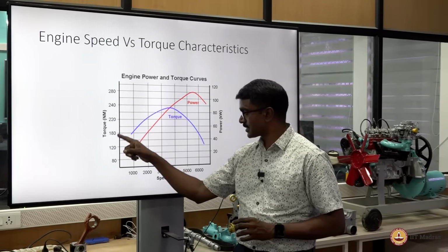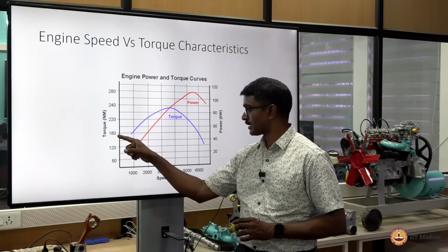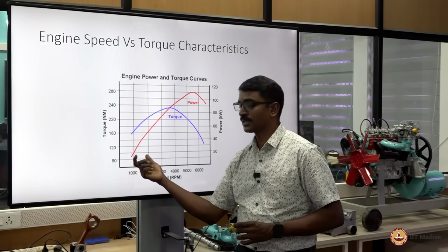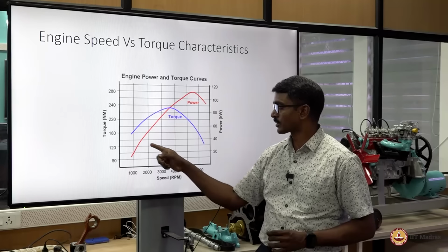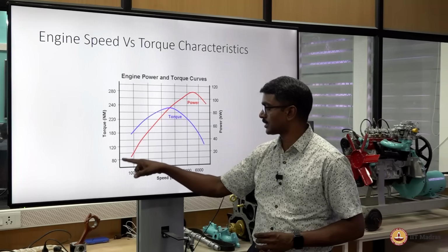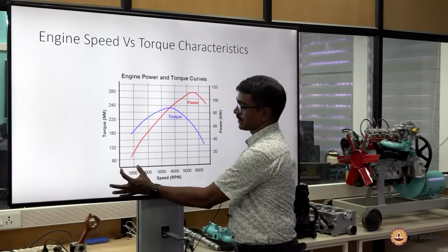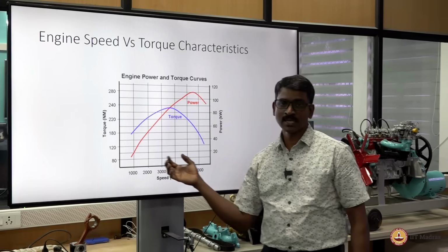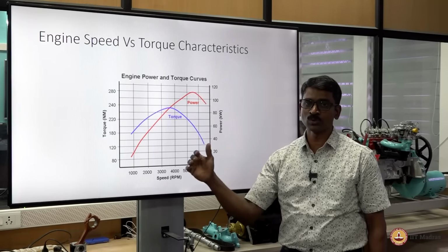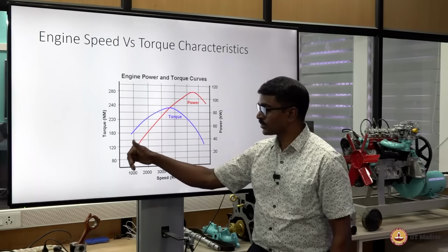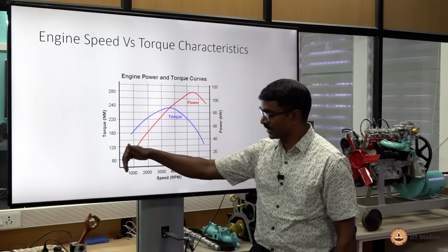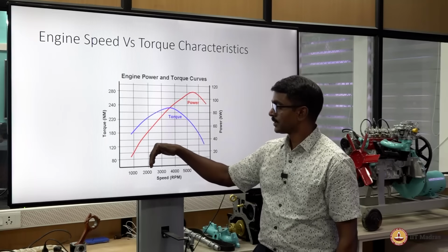First we will discuss this particular gap in torque and power, which demands a clutch, a move-off element. Without a clutch, as you see, there is no torque and no power in this region. Because of this, a clutch becomes necessary to move the vehicle. The clutch is also called a move-off element that is used to move the vehicle at near zero speeds.